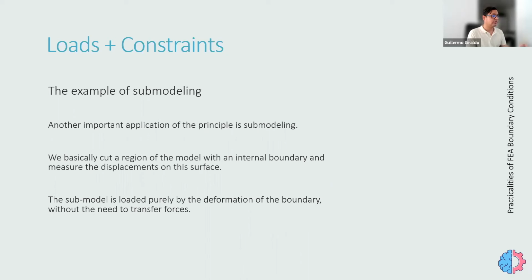So in submodeling, they also apply a principle that is very close to what we have been talking about until now, to overcome the numerical difficulties of solving a system with not enough constraints, or a system that has rigid body motions and is not properly constrained. Again, remember the other case of the displacement-driven nonlinear simulation, when we are also fighting the solver, which cannot easily converge sometimes under force loadings.